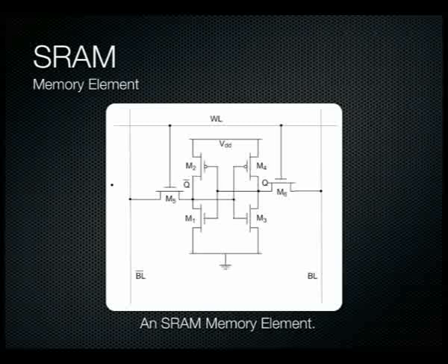So in our microprocessor, when we have our register sets made up of these sort of SRAM-like elements, we can quite easily get the not out of a particular register simply by latching the other output line. So instead of latching the bit line, we can latch the not bit line through a multiplexer to the actual data bus. So we can quite easily do a not inside a microprocessor just simply by latching the other output line. So an SRAM element consists of effectively 6 transistors, quite a lot of space on the silicon wafer.